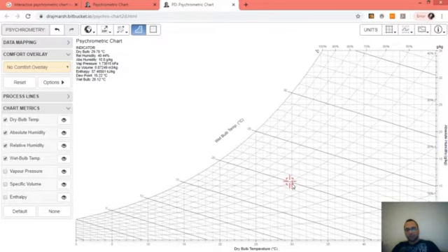The evaporative cooling process is when you introduce water vapor, or when water evaporates within an air volume. When water evaporates, the heat of vaporization is taken from the air, so the air temperature drops. Its relative humidity increases, its absolute humidity increases as well.